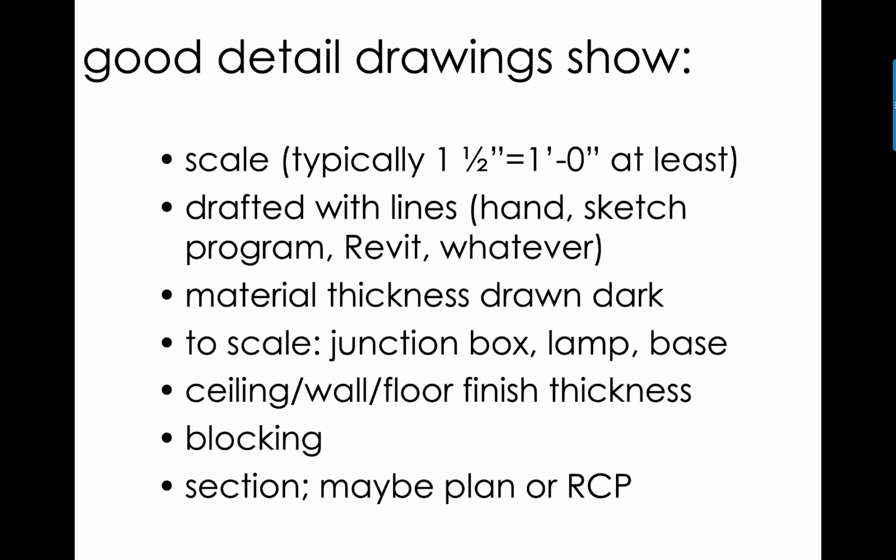But obviously use your proper detailing conventions: dark lines for objects that are cut through, light lines for things that are in the distance. And you should show a junction box, and if there is a lamp, the base should be the correct size. You can go onto something like lamps.com and find a million different sized lamps if you're looking for something that fits into a very specific spot. So finally, blocking, all those sorts of things are very important.